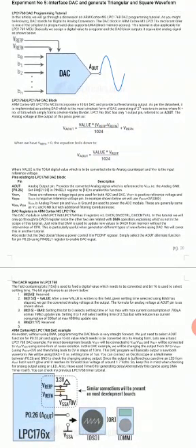Each pin of the ARM Cortex M3 has 4 functions. Either it can be used as general purpose input output, or as some other function. Here P0.26 is used as a general purpose input output in the case of LED, or it can be used as the AOUT pin.